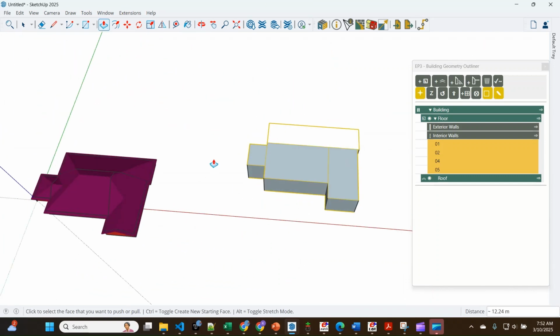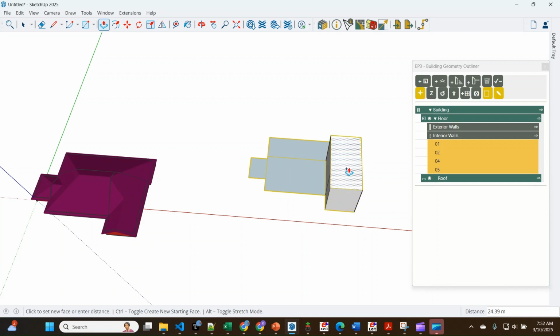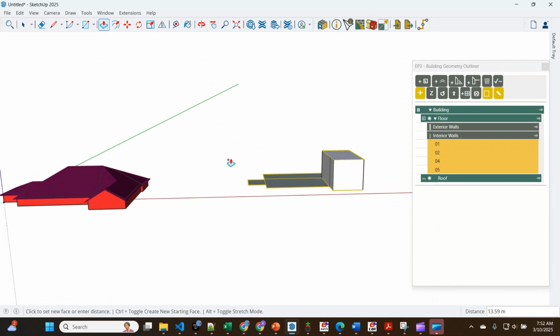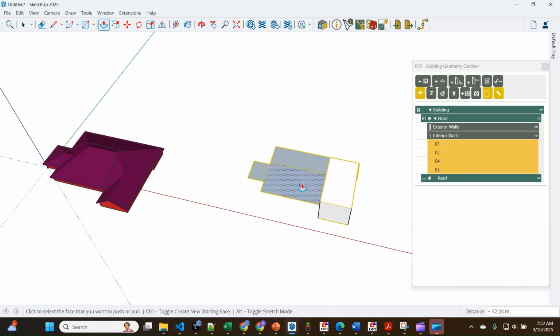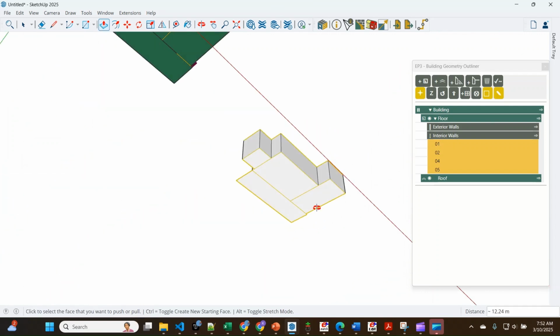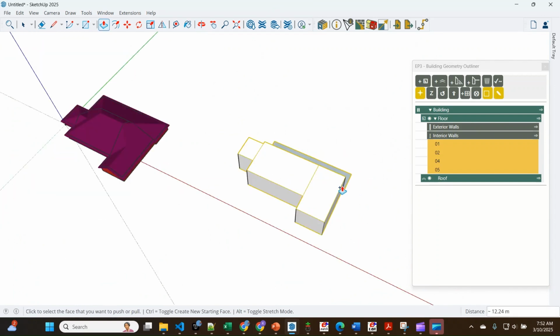If you notice in the SketchUp to IESVE video, they had the push tool working in copy mode, so it generates the floor as well. You have to catch that before you get too far, otherwise you may have to go back and redo a lot of work. Okay, so now we're actually pushing up, and you can see that we're maintaining that floor section.